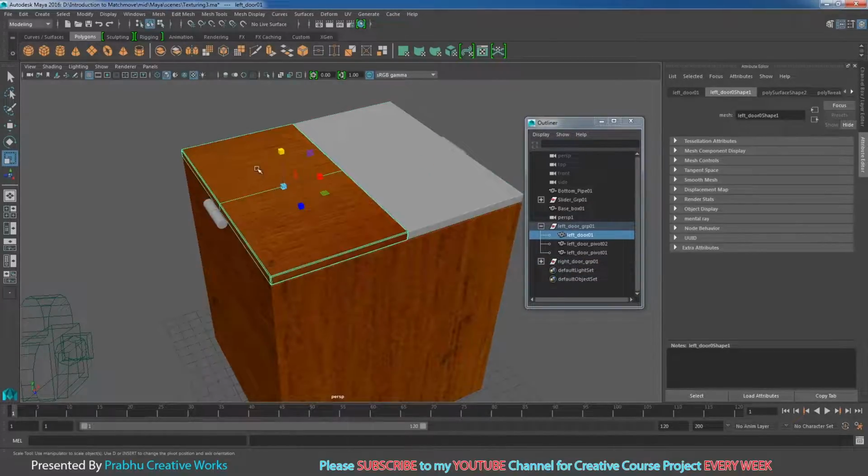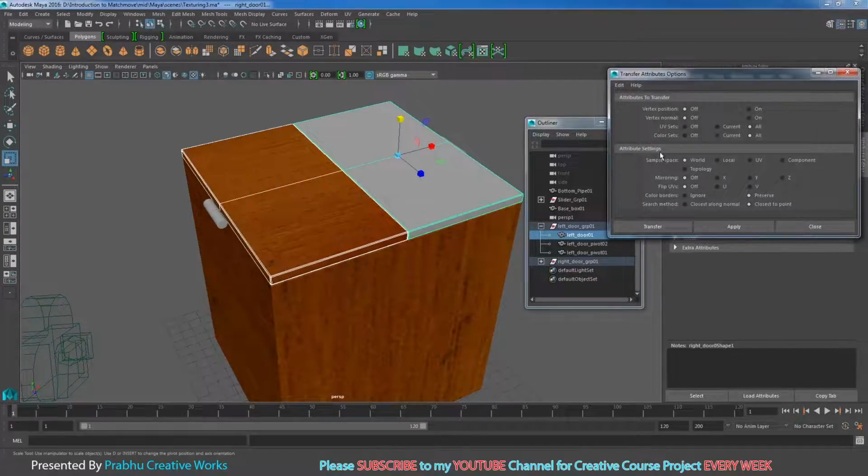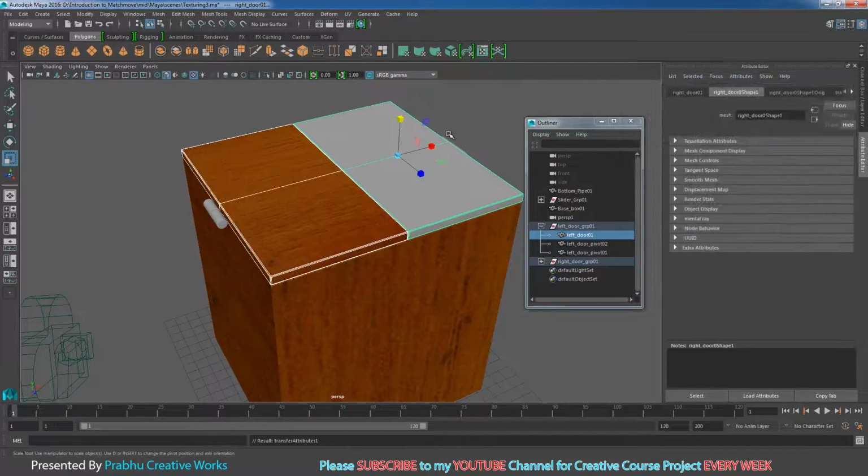First you want to select the textured mesh, and shift select the untextured mesh, and go to Mesh and choose Transfer Attributes. Now I want to set color sets to off, UV sets to all, and color sets to off, and choose component. Here you need to choose component and choose transfer.